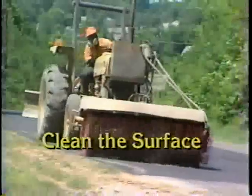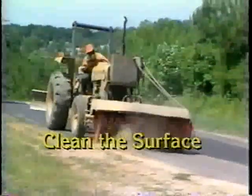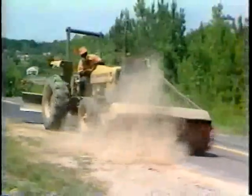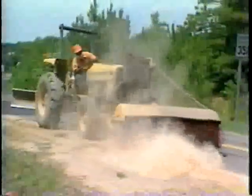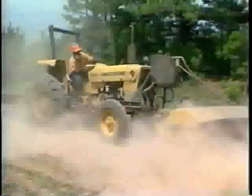The third step in the asphalt chip seal procedure is clean the surface. Clean the surface prior to spraying asphalt. Cleaning is usually performed with a tractor-mounted power broom. This is effective for removing loose sand, stones, and debris. Remove hardened mud and other foreign matter before the seal is installed. The objective is to provide a clean pavement surface for the asphalt to bond with.